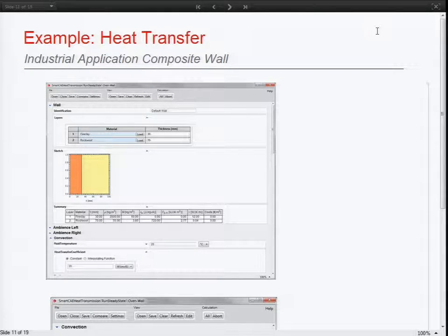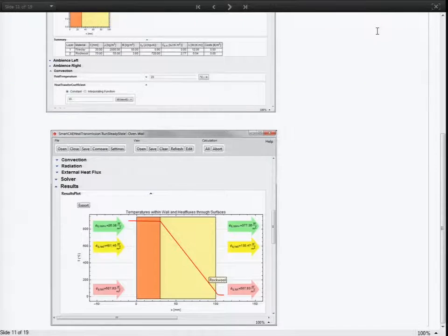But you see that it's not interactive now, but you can just add rows here to add layers, and you can just choose from a material. You can define your own materials. You can read the material properties from an Excel file from measurements. So you have temperature-dependent material data and all these kinds of things.